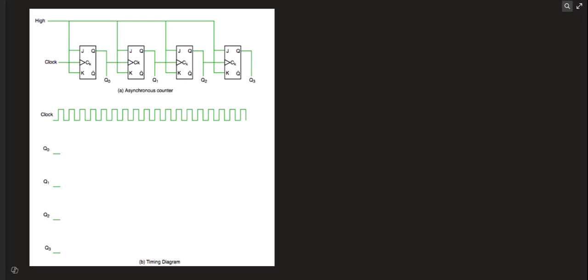T flip-flop, right. So J is set, so J makes it 1, K makes it 0, or the other way around, I can never remember. If they're both 0, it's no change, but if they're both 1, then it's a toggle. So this means that every time it'll toggle whatever it was before if you're on the positive edge of a clock cycle. And how do you determine if you're on the positive edge of a clock cycle? When it switches from low to high? When your clock signal switches from low to high.